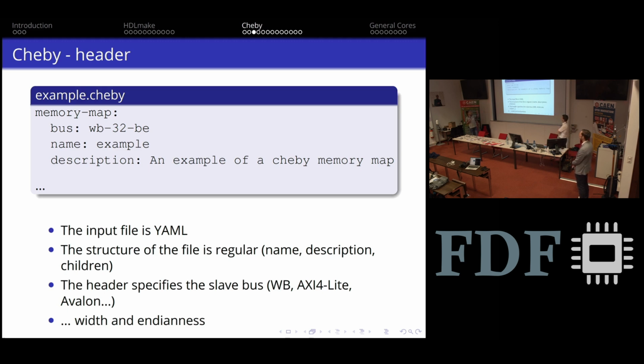From this example, we generate one file, which could be a VHDL, Verilog or SystemVerilog file, and at the top you have clock and reset, and you have your main bus, so Wishbone or AXI4, and then you have inputs or outputs or a bus for every register. If you also add a submap, it can also create a bus to connect to another core. And an interesting feature is that the tool is able to convert from, for example, Wishbone to AXI4. There is no problem with that.